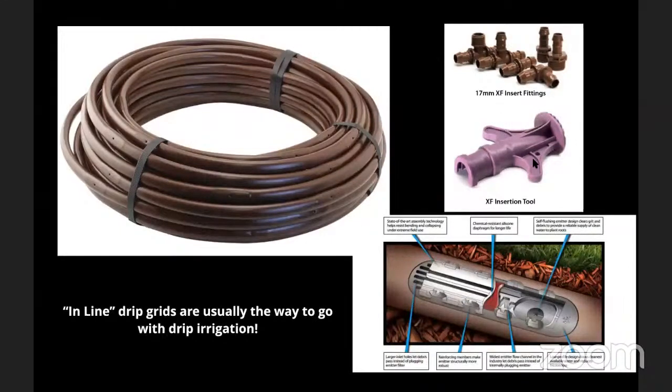And then you can also use these little side pieces, which your fingers go into for that leverage, to kind of, when you cut the line, loosen the opening a little bit before you snap it in and push it in. So for homeowners, if it's your first time, those Rainbird fittings do work pretty nicely.